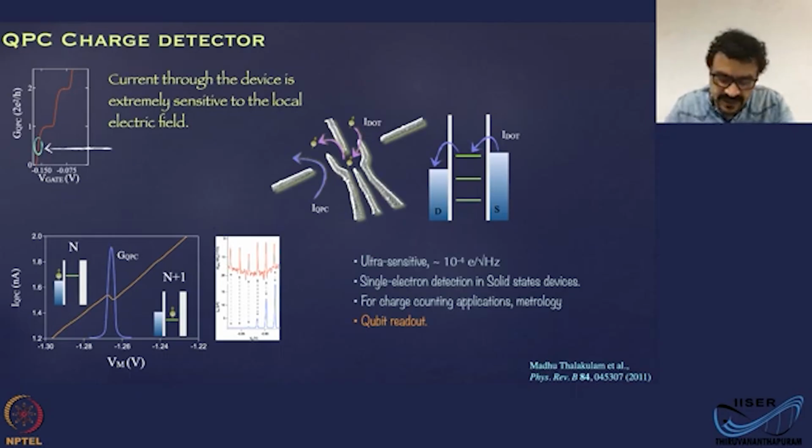If you look at the transconductance, that is, the gate voltage versus the current through the system, or conductance, there are really nonlinear, very sharp drops in the current, where a small change in the gate voltage can give you a large change in the conduction.